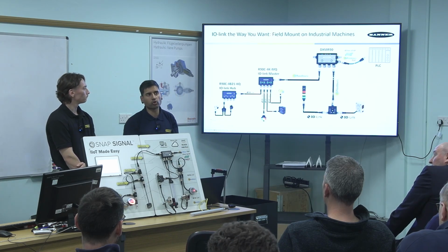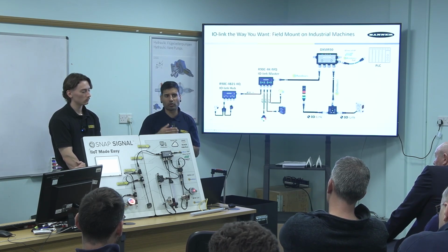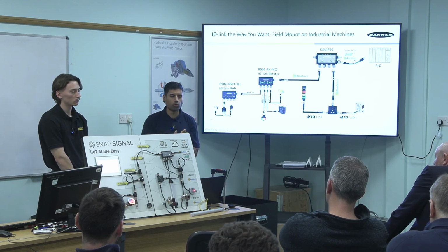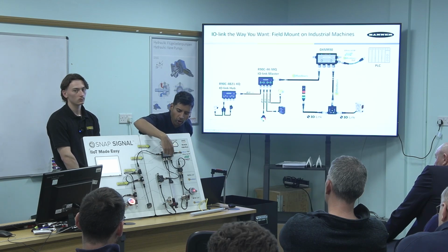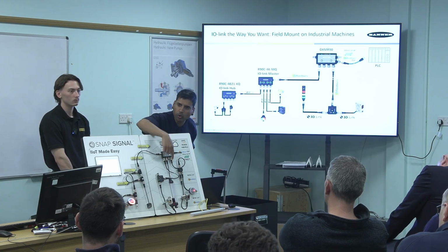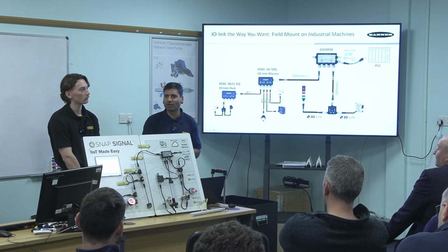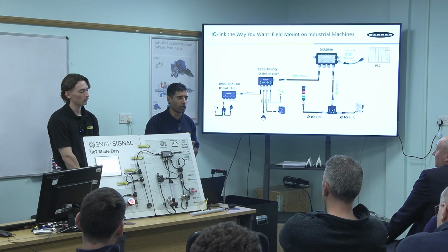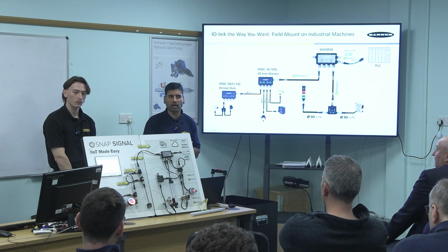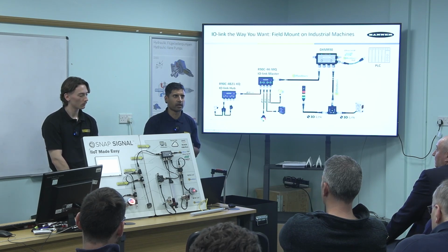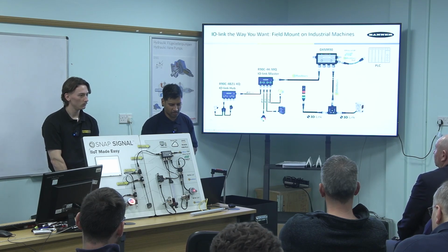That's right, yeah. That's a good point, actually, because per controller, you're limited to 4 amps. So you just got to be aware, even though it's Modbus, we go with the Modbus rule, so you can have up to 247 devices connected to that, on each of these RTU ports. But realistically, that's not going to happen because you're going to consume power. I know sensors don't take up much power, but some of our lighting does. So you just got to bear that in mind. But it uses all the Modbus rules. It's 1,200 meters, up to 247 devices, depending on how much current they're going to consume.